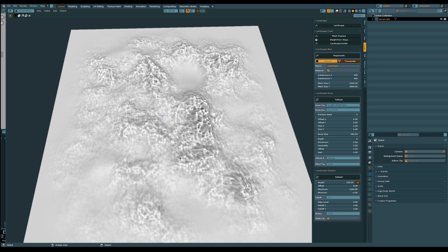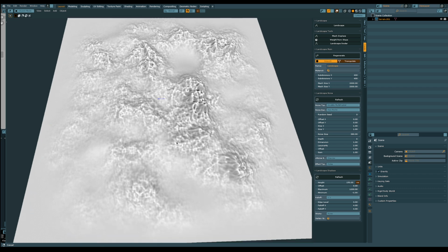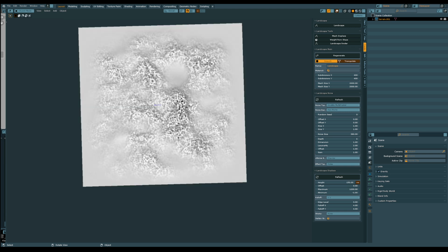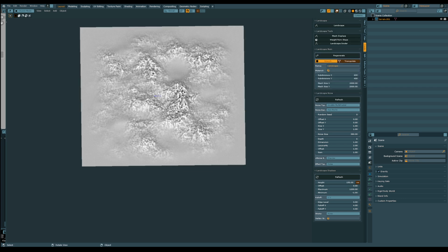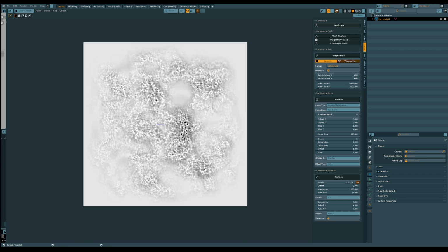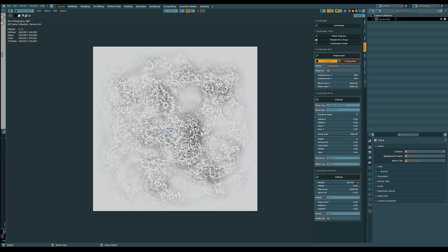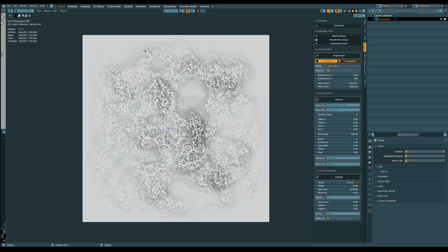All right, now we have the terrain. If you have a full-size keyboard, press number 5 on the keyboard. That will switch you to orthographic. The way to know you switched to orthographic is to hold Alt, and if you have the options to show text info and statistics enabled, it will tell you it's orthographic 180. It's very important to do that because we're going to be drawing the roads, and you need to look at it from the top.